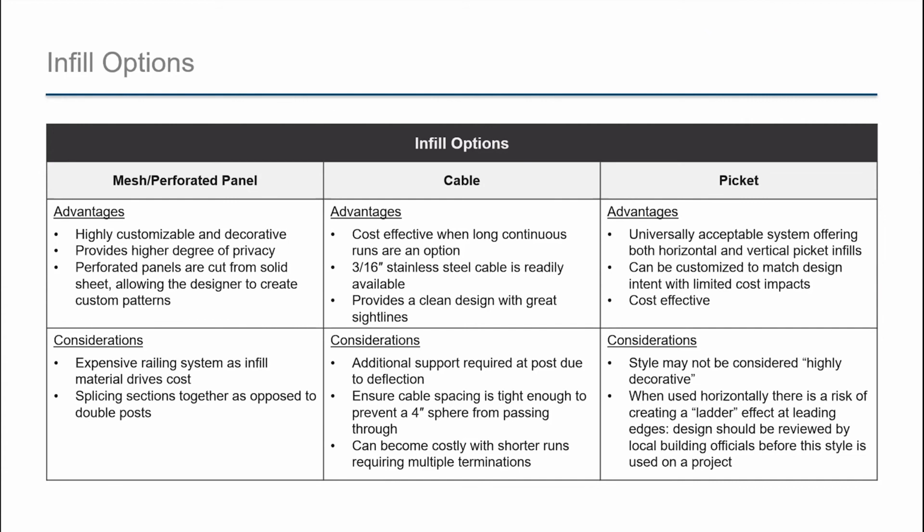However, cable infill panels also come with engineering challenges in terms of loading. In order to address deflection in this material type, it is important you specify 3 1/4 inch cable to cable spacing horizontally. This is a common oversight in most bidding documents and can lead to costly mistakes if not specified correctly.